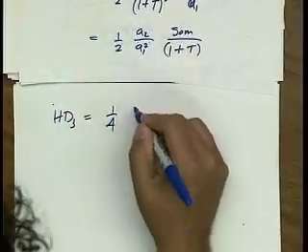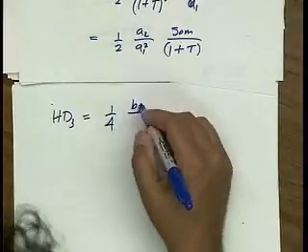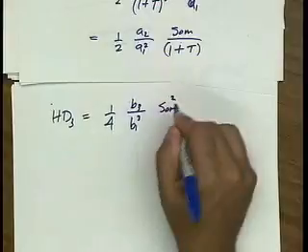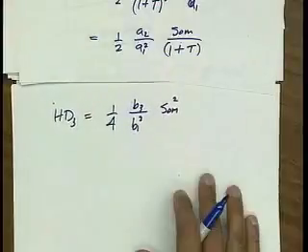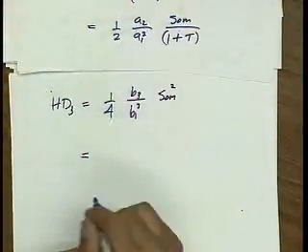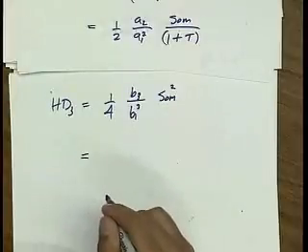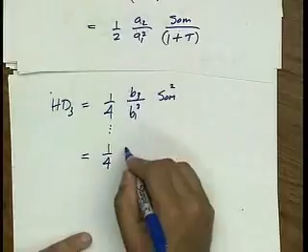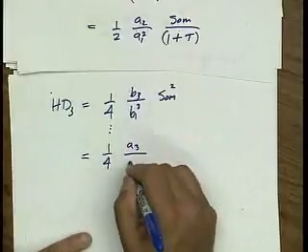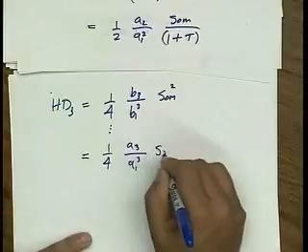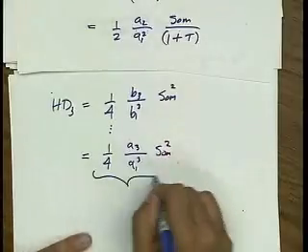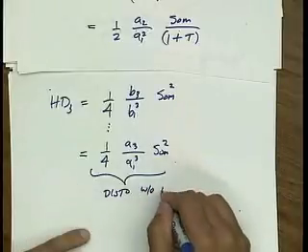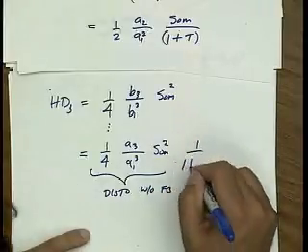HD3, which we derived last lecture in terms of the output, is B3 over B1 cubed times the output level squared. And I plug in all the equations that I derived. Again, I won't bore you with algebra. I like to write the answer in terms of the distortion of the circuit without feedback, times 1 plus t.